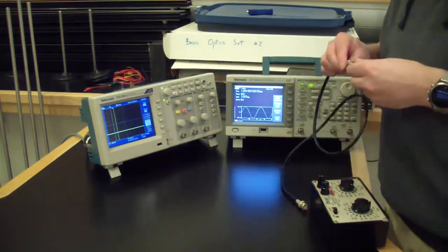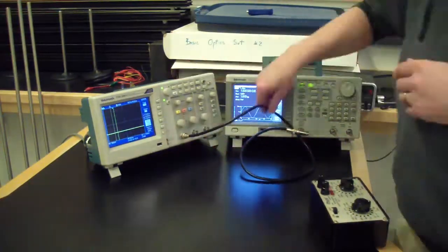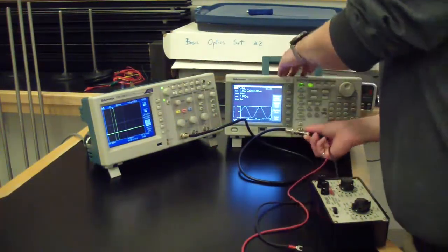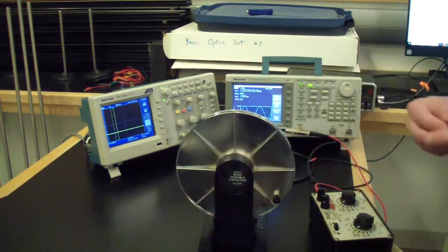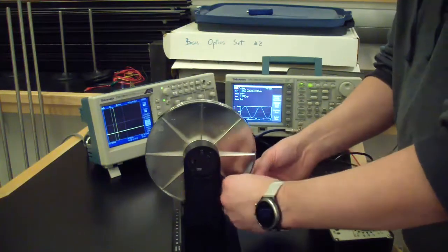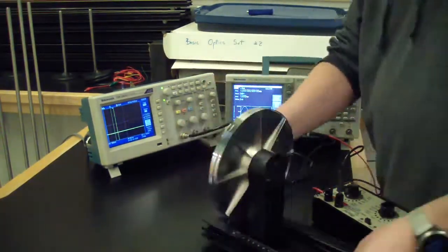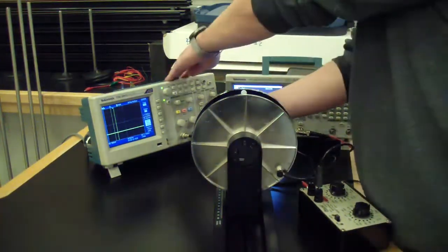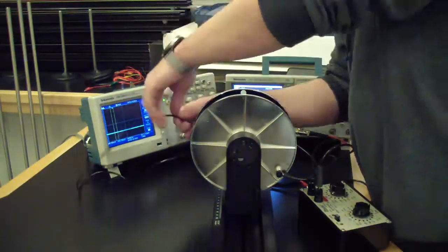To start, we'll connect the circuit. Place a T connector on the function generator output. This way we can monitor the signal we drive the circuit with as well as its response. One end of the T should go to channel 1 of the oscilloscope with a BNC cable. Attach the red positive pin of the other end to the resistor box. Attach the other resistor box terminal to one of the plates, and attach the other plate back to the negative pin of the function generator.